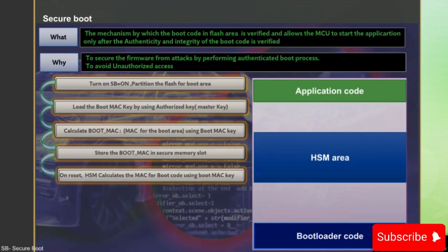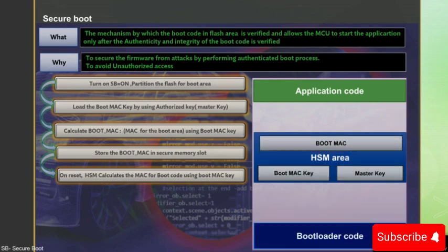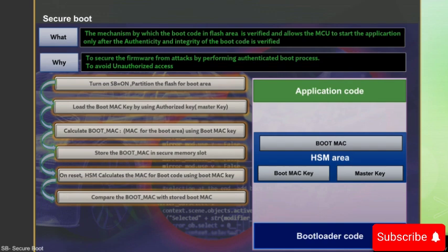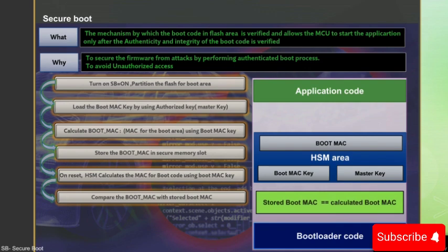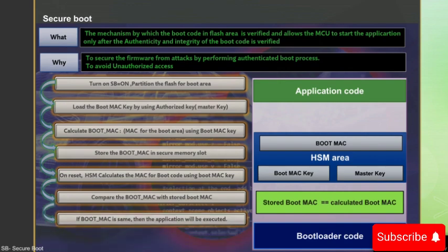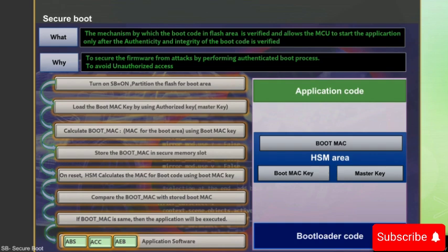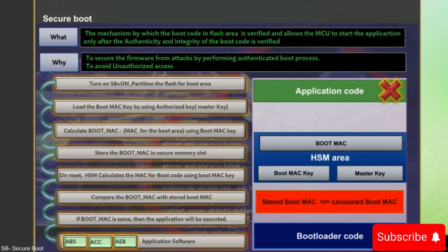On reset, the HSM calculates the boot MAC again for the boot code using the boot MAC key. Then the secure boot will compare the calculated boot MAC with the stored boot MAC. If the stored boot MAC and the boot MAC calculated on reset are the same, then the application will be executed. So let's see a negative scenario where the boot MAC calculated after the reset is not the same as the stored boot MAC.